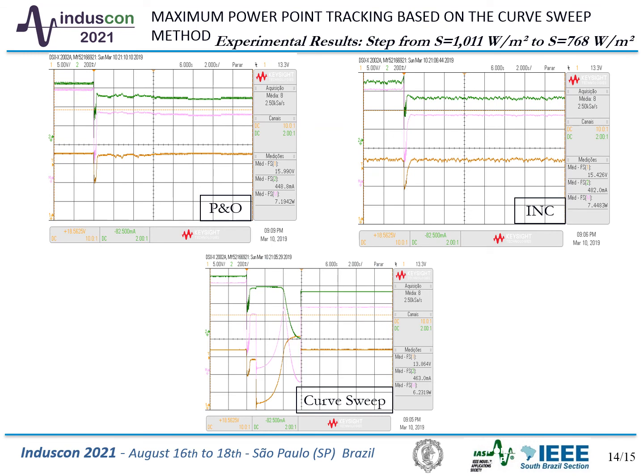Dynamical tests were also performed, in which the irradiance is suddenly decreased. As expected, P&O and INC present an oscillatory behavior of the extracted power. This undesirable behavior is not observed in the proposed technique. However, it takes longer to sweep the whole current versus voltage characteristic. Therefore, the resulting efficiency is lower than those obtained with P&O and INC. Every time the climatic condition changes, it is necessary to sweep the curve again. However, the introduced technique can determine the maximum power accurately for any operating condition, including partial shading.